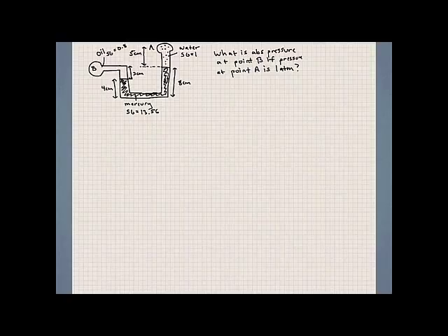So, what I want to start with is this manometer problem. So let's look at it. In the container B, we have a pressure in there, and in container B, up to the interface of where this black squiggly line starts, we have oil. The black section that I've colored in is mercury, all the way up to the spotted section, which I've designated as water. Now, something you'll notice is that each one of these has its own designated specific gravity.